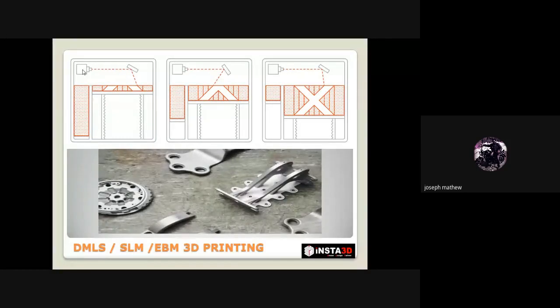Below shown are the different 3D printed metal components which are made out of a SLM or DMLS 3D printer. You can ask, when can I go for a DMLS or a SLM or EBM 3D printed component? For one with difficult, intricate or complex geometry, you can go for metal 3D printing. Otherwise, you can go for conventional manufacturing processes because the cost involved in DMLS and SLM is very high, and the material availability is also very less in case of DMLS and SLM techniques.